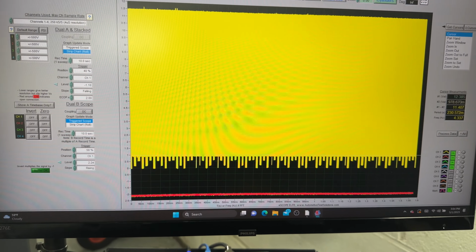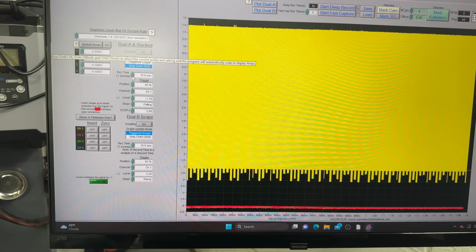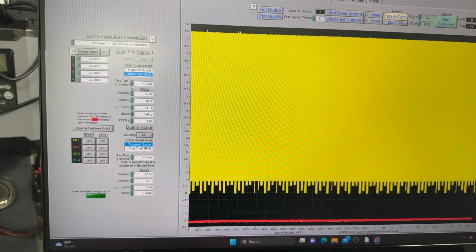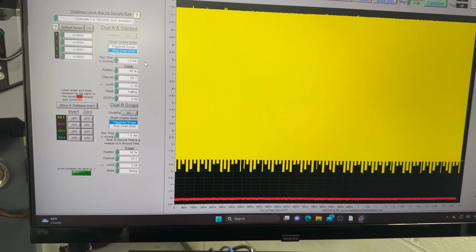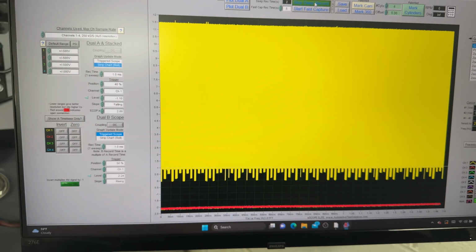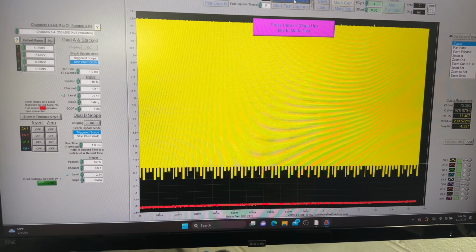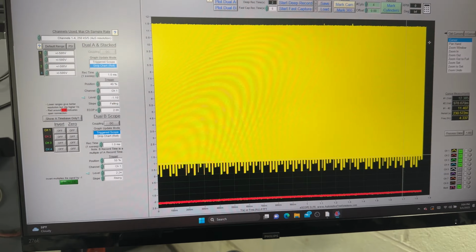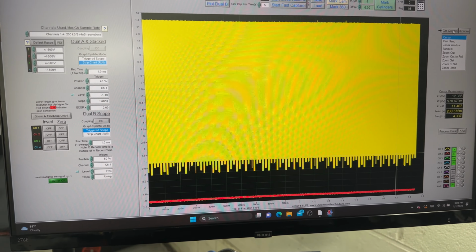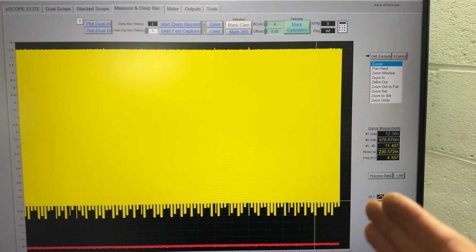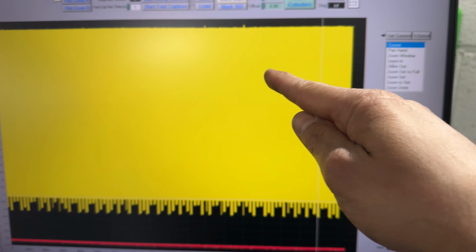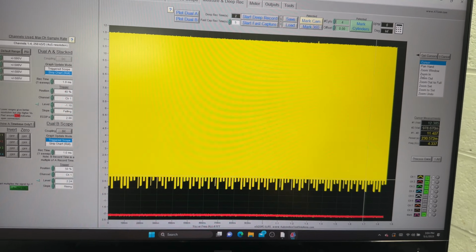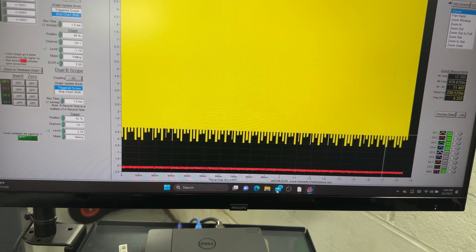So if you're using the ATS scope, what you need to do is reduce the sample rate in here, the recording time. In this case, I'm recording a really fast signal, so I want to use 1 millisecond. And I can even leave the 500 volts. I don't think that's going to affect anything. You see? Because right now, even at 500 volts, I can definitely see that signal complete. I can get the cursors. If you use an ATS and you don't have that zero cursor, go over to the ATS Facebook page and look for the, let me show you. I think I still have it open.